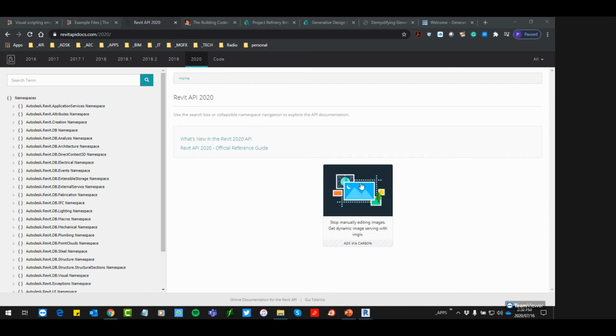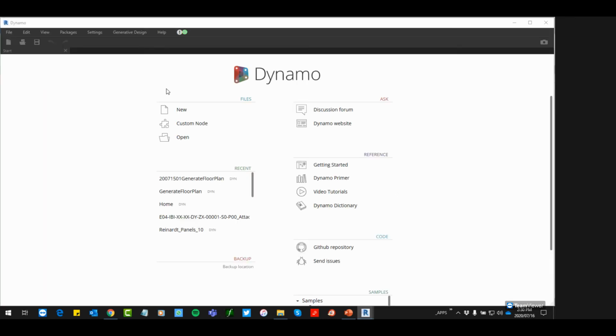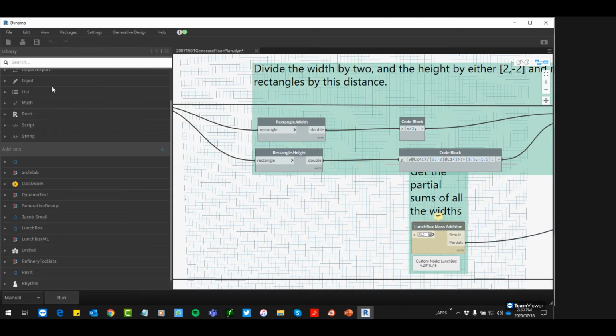So just to recap, we've been talking about Revit, and the topic is generative design. And just as a recap, in Revit we've got Dynamo. And when we open Dynamo, we can create scripts. And within the scripts, in the graphs, we can also include nodes that reference the API over and above the nodes that we get natively from within Revit, and also what we get from packages.